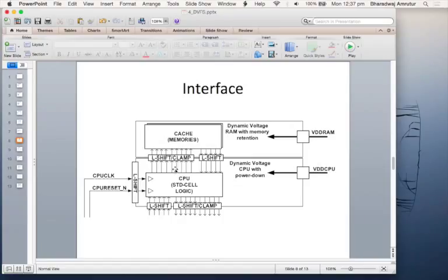In the case of a NAND gate, if one of the inputs is 0, the output will be VDD no matter what the other input is. So even if the other input's voltage is slowly creeping down with time, it doesn't matter. The output is held properly. So like that, you have to put some gate to clamp the voltage at the output of the level shifter.